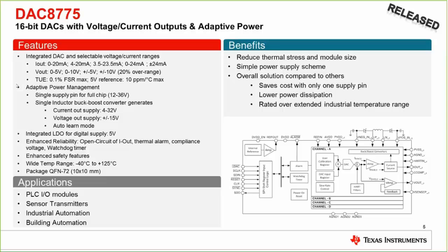Clamp mode kind of changes the operating corner a little bit, basically by reducing the minimum voltage that the DC-DC would output. So suppose you're using this device with known loads and known maximum output currents, and you don't want to deal with full tracking mode, you would just set this clamp voltage and it would maybe never change.